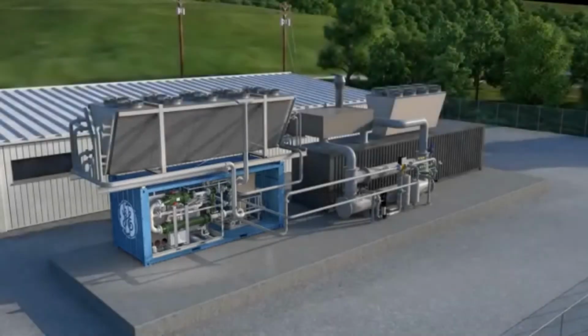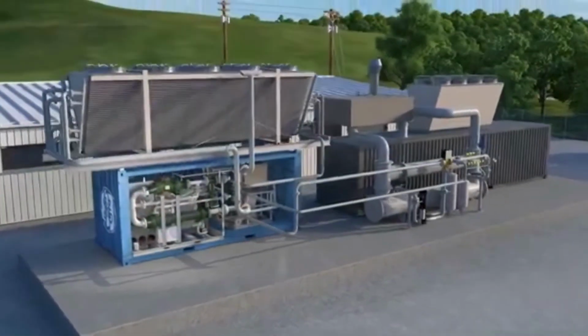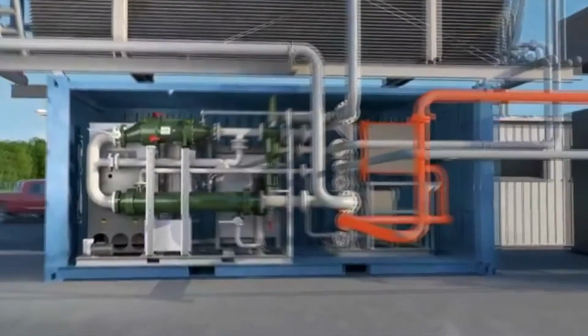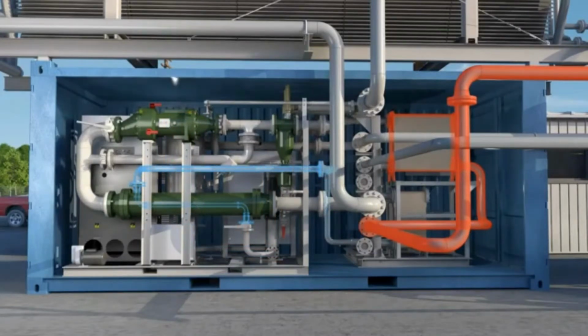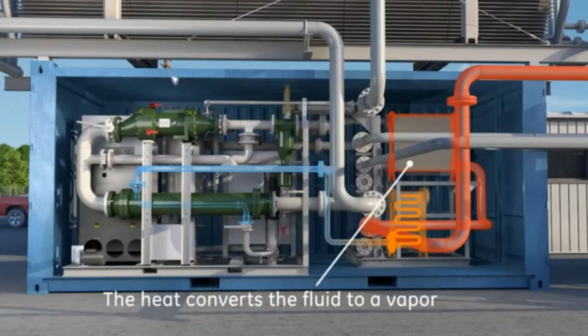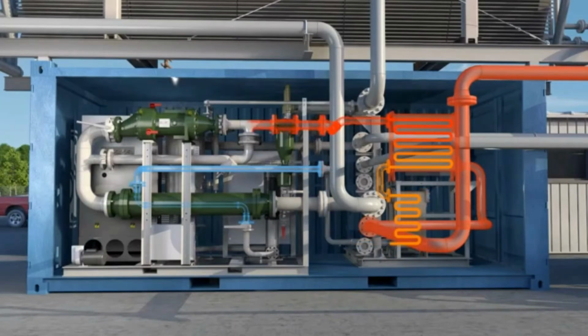Vapor or saturated vapor or superheated vapor from the boiler at state 1 or stream 1, having an elevated temperature and pressure, expand through the turbine to produce work that connect to generator for produce electrical energy, and then is discharged exhaust gas or vapor to the condenser at state 2 with relatively low pressure, neglecting heat transfer with the surrounding. The mass energy rate balance for a control volume around the turbine reduces at steady state to give Wt per m equal to h1 minus h2.